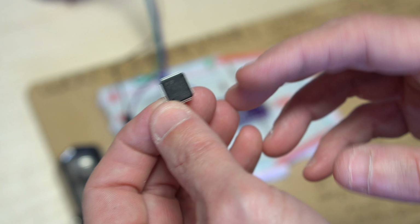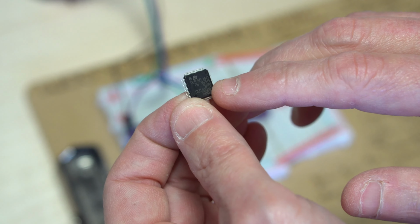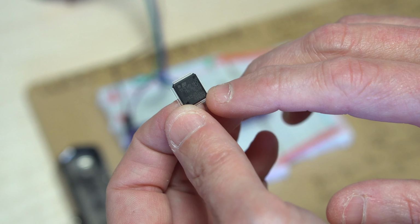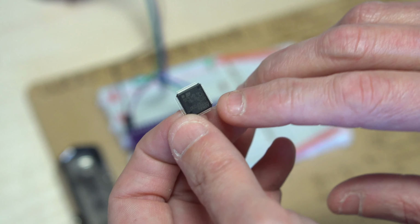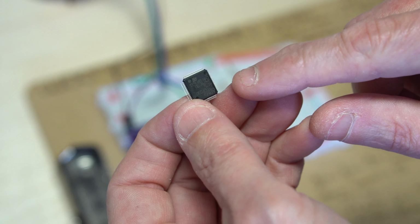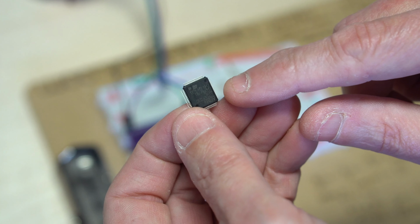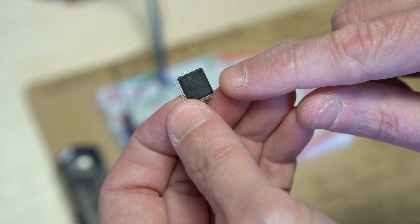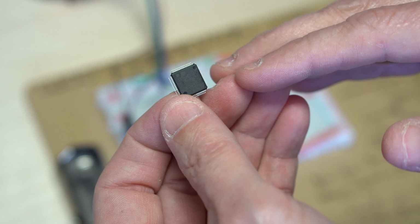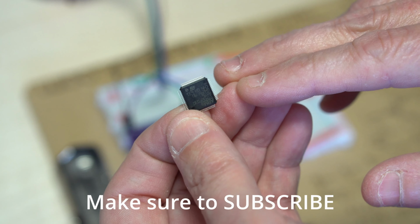In this video, I'm going to show you how to change the clock speed of the microcontroller from 8 MHz to 48 MHz. This is an STM32 F030 microcontroller. The STM microcontrollers have an internal clock and an external clock, and each of these clocks have a low speed and a high speed. The high speed internal clock is the HSI, and the low speed internal clock is the LSI. The external ones, which we'll talk about in another video, are the HSE, which is high speed external, and LSE, which is low speed external.